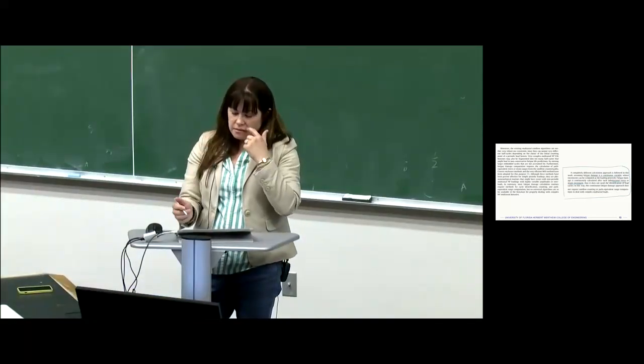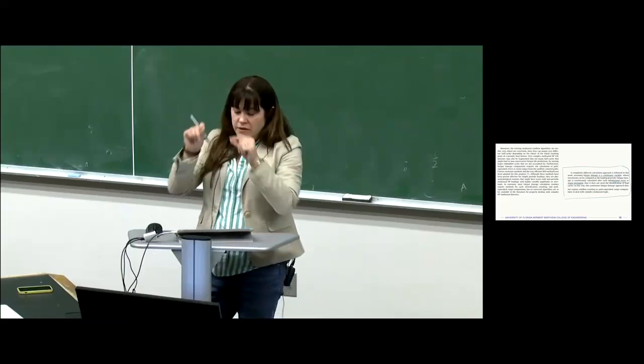We're throwing out any type of background of this whole stress-life approach, which is to say, what's the stress and how many cycles can you sustain at that stress, right? So it's kind of a big shift, could be a very big shift in the thinking about the accumulation of fatigue damage. And so they're saying that they don't care about a full loading cycle to add to the damage. What they're saying is that infinitesimally small stress or strain increments, so even a portion of a load cycle would count toward the accumulated damage. And then the next little portion of the load cycle, such that infinitesimally small portions of all of these curves would add up into some damage.